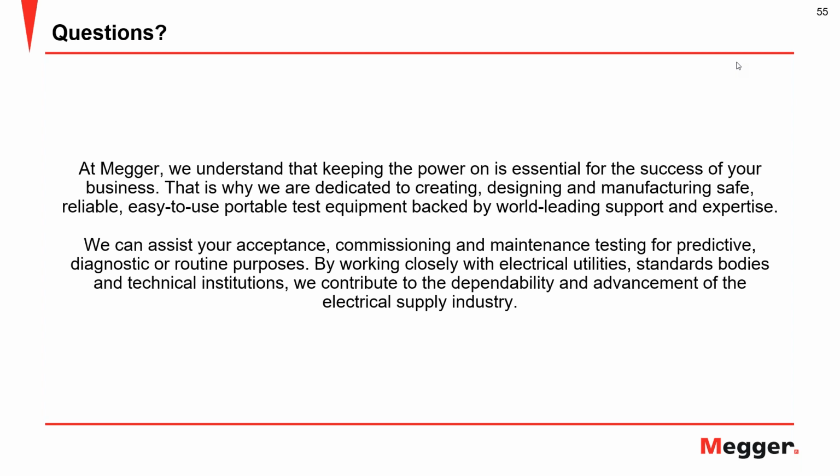So it's very important, when performing offline partial discharge testing, to take both the inception and extinction voltage measurements, as this condition may happen, and one may think that the inception voltage is above operating and everything's okay, and then one day the cable fails due to partial discharge because the extinction voltage was below that. So really good comment, and I just wanted to elaborate on that for anyone else as well.